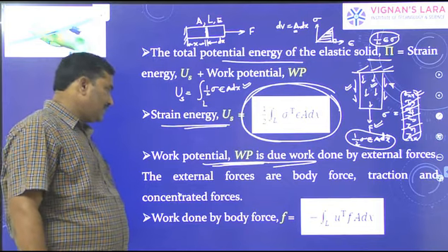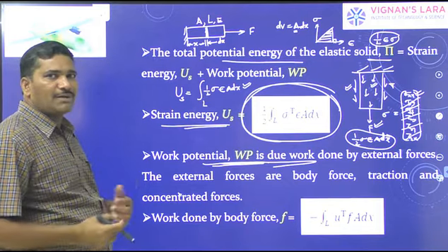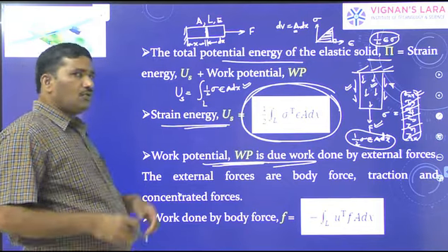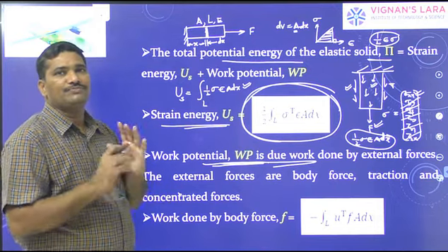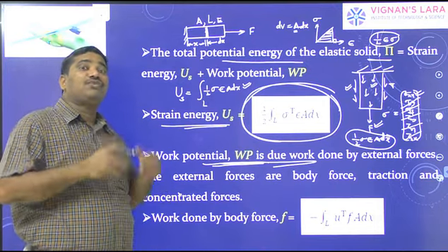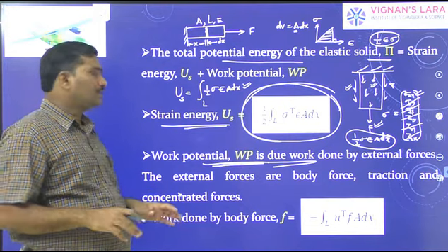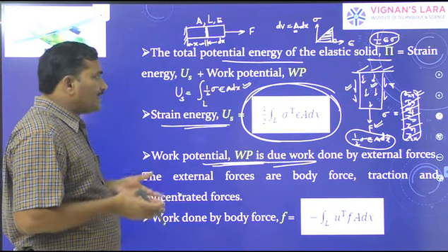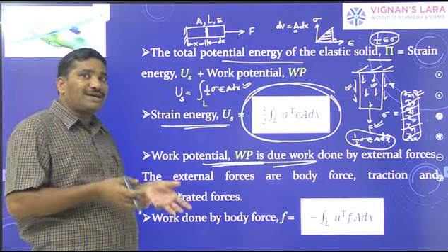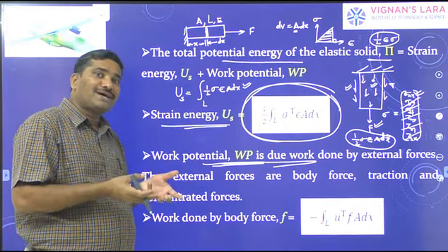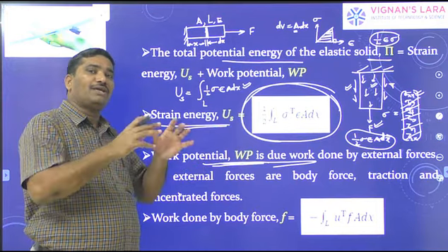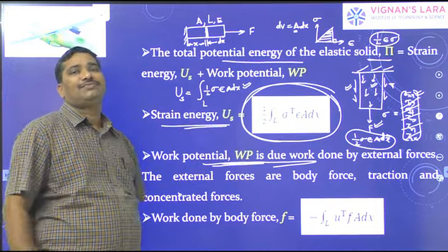So firstly we see the work done by the body force. Work done by external forces is considered negative and work done by internal forces is positive. So what are the internal forces here? The forces that are set up against the external forces. The forces that are set up inside the body against the external forces.